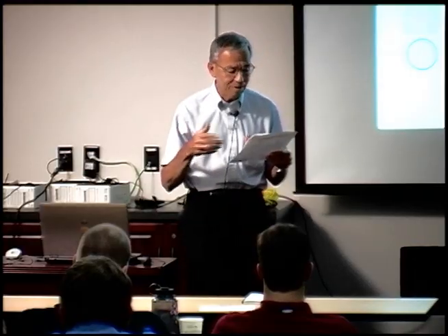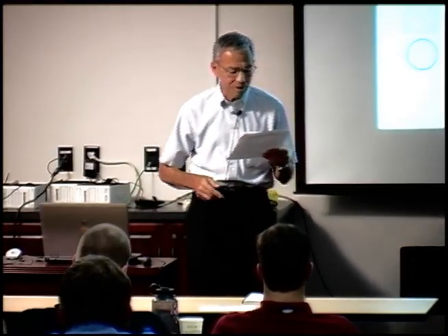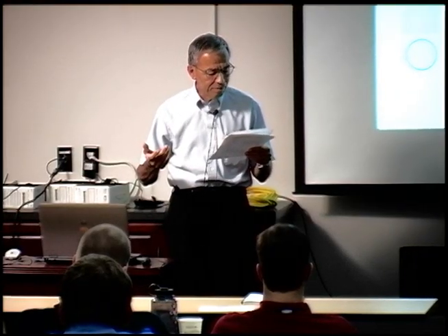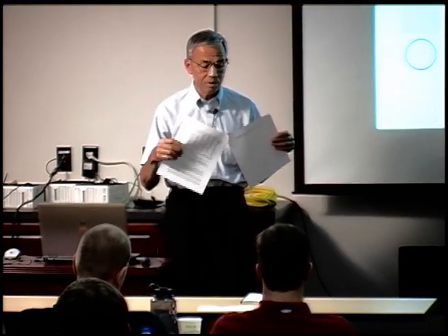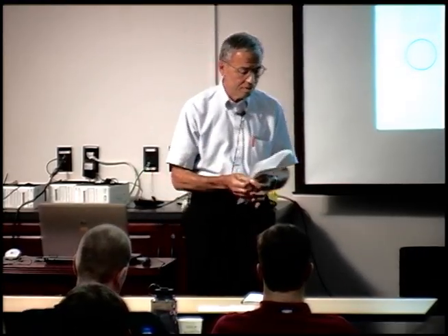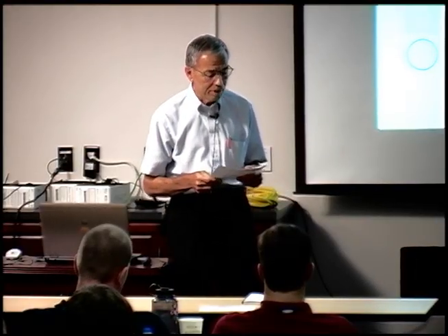Generally, if you take an average, and this of course is a very small sample, it took about 84% of the plan length to get bearing for abutments and about 69% of length to get bearing for piers. So piers reach bearing a little bit quicker than the abutments.